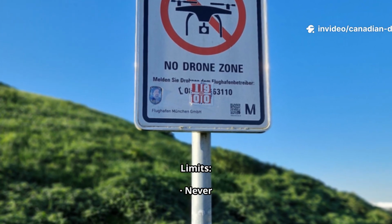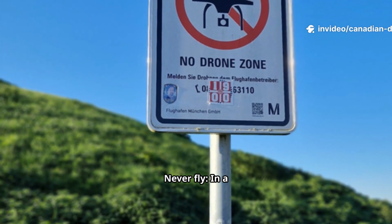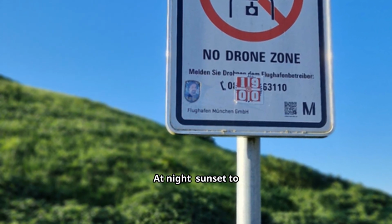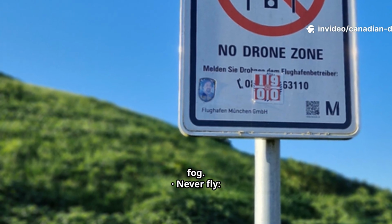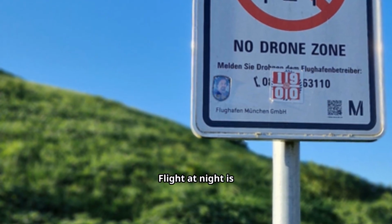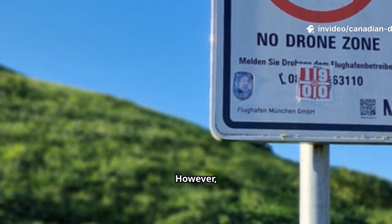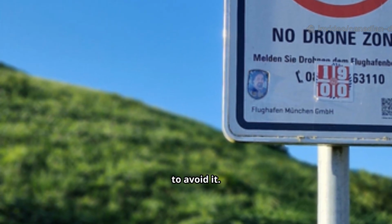D. Operational limits. Never fly over or within 30 m of bystanders. Never fly in a reckless or negligent manner that endangers aviation safety or people. Never fly at night, sunset to sunrise. Never fly in clouds or fog. Never fly where it could interfere with police or first responders. Note, flight at night is technically possible under basic rules if the drone weighs under 1 kilogram and has lights allowing you to maintain VLOS. However, it is a high-risk operation and heavily tested. The safest answer for a new pilot is to avoid it.